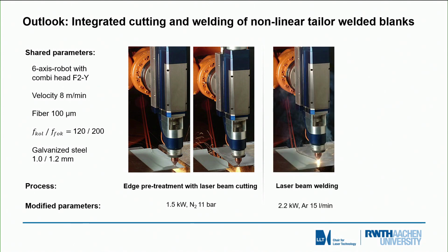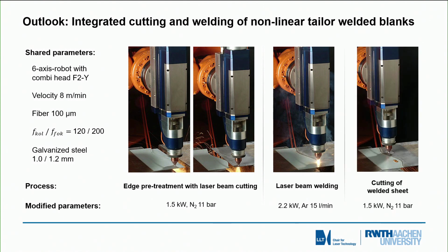And then in the next step we put the two parts together and weld them with the same control data. Ultimately, additional functionalities can be brought into these sheets, like you see here some elliptical cuts, which of course now have a 100% precision repeatability, because all the distortion of the welding takes place before we bring in the cuts of these shapes. So laser cutting, as said, is the most used laser application today, and it probably will remain very much used also in the future.